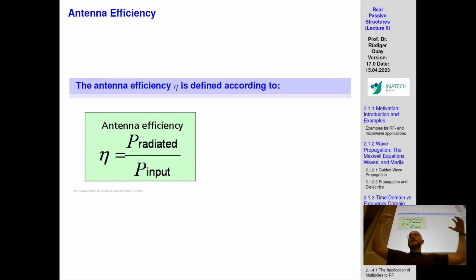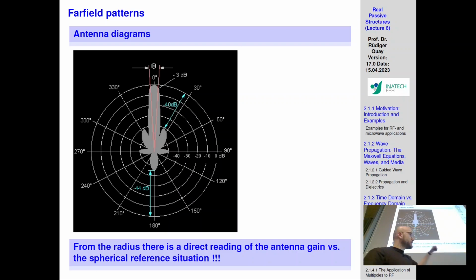These waves that come in need to see a certain match. You're matching with a complex conjugate to be able to transfer most of the energy towards the next medium. In order to transfer this energy, you have to have a good input matching of the antenna, and that's why it's very relevant how much energy your antenna accepts and how much it radiates, and that radiation depends on how many losses it has. This is the plot. As I said, this is important. These parameters, directivity, gain, aperture, are important for the exam.